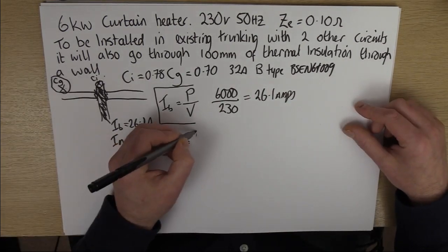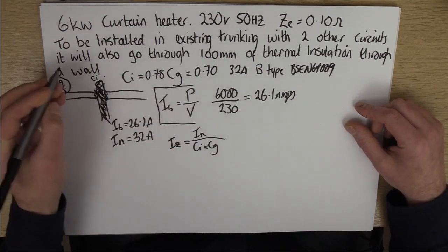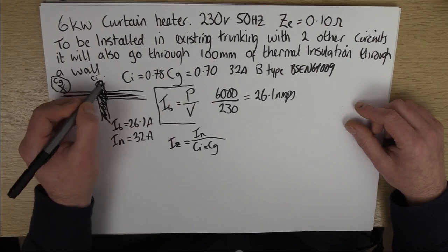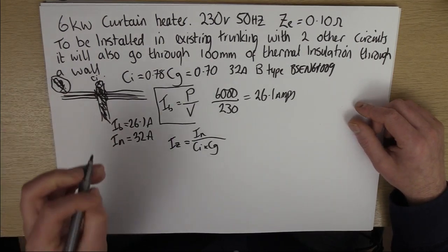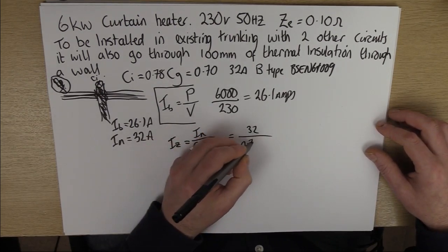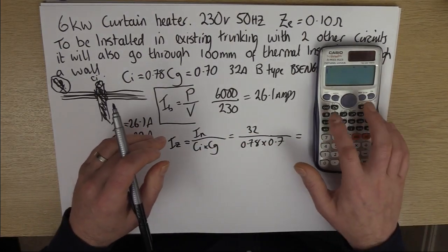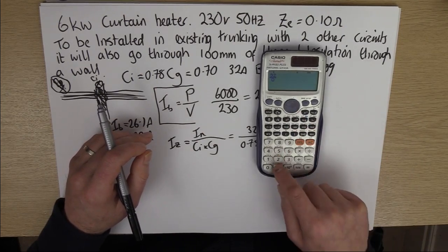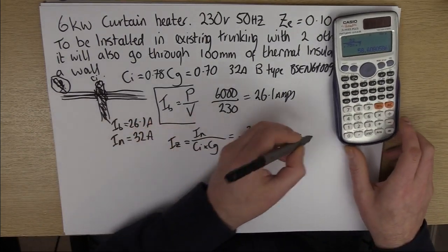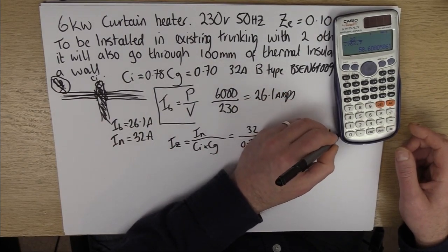That's the idea. And so in our case, we are going to apply these together because the grouping is there. We've got the circuits running through and the insulation is there. So unfortunately, that's what we're going to have to do. So we've got 32.78 times 0.7, which gives us an IZ of probably quite a lot. 58.6. Wow, that's what it says.